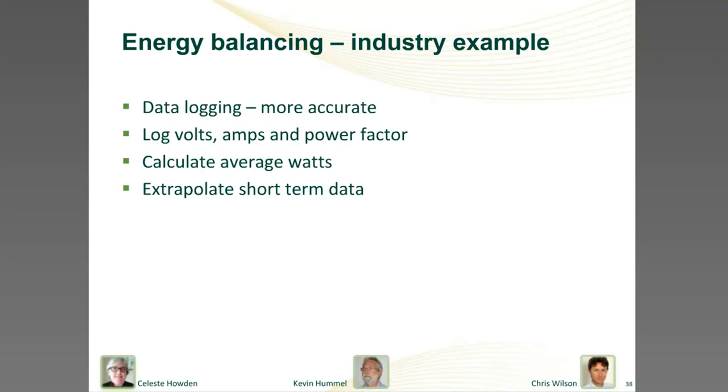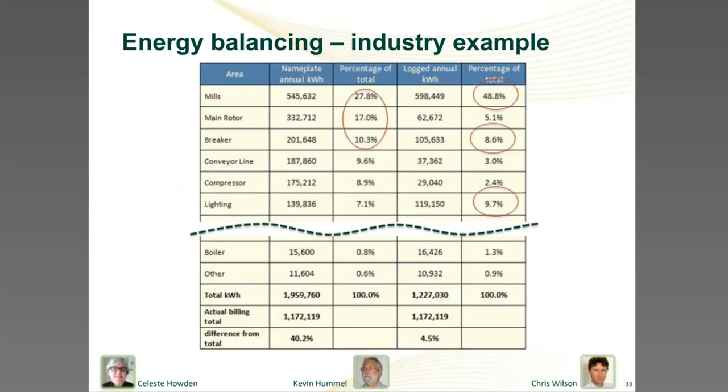The logging will give several outputs. These are generally uniform and relate to the voltage in volts, the current, which is in amps, and the power factor. If the equipment is running on 3 phases, then each phase will have a separate output. Taking the average value over the recorded period for each unit and multiplying will determine the average kilowatt power rating.